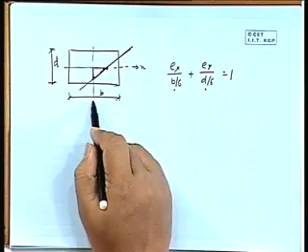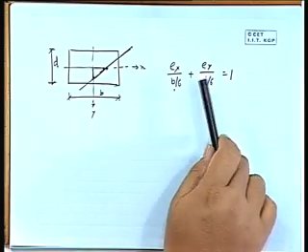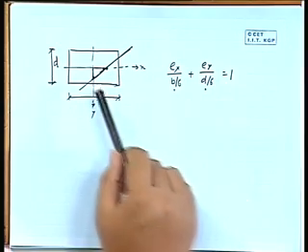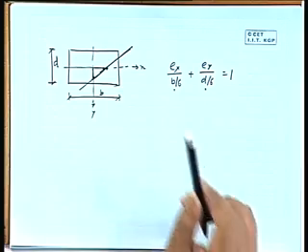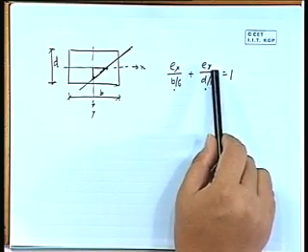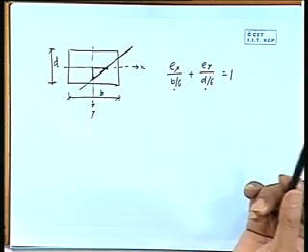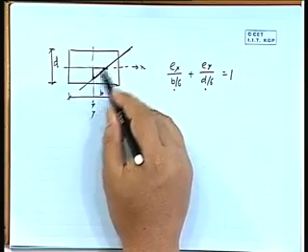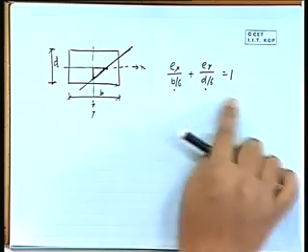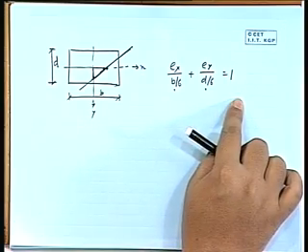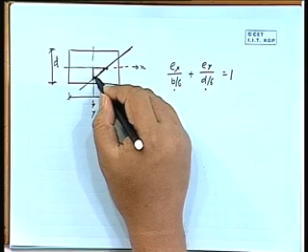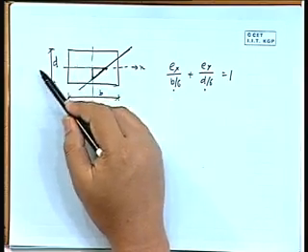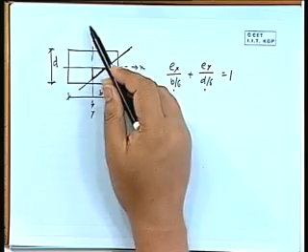So it is x, it was y. Say Ey is equal to 0, only Ex is there. So Ex equal to b by 6, that you have already obtained. Or if Ex equal to 0, Ey will be d by 6, that also you have determined. If you just join these 2 points, there will be a line, and that is the equation of that line.